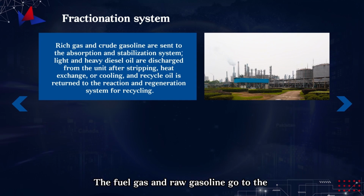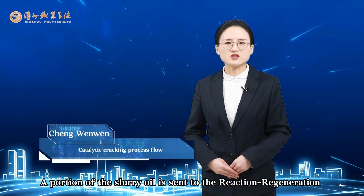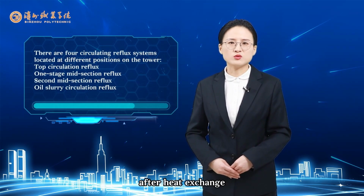The fuel gas and raw gasoline go to the absorption stabilization system. Light and heavy diesel are sent out of the unit after heat exchange or cooling. Recycled oil returns to the reaction regeneration system for recycling. A portion of the slurry oil is sent to the reaction regeneration system for recycling. Another portion is circulated back to the fractionator after heat exchange.